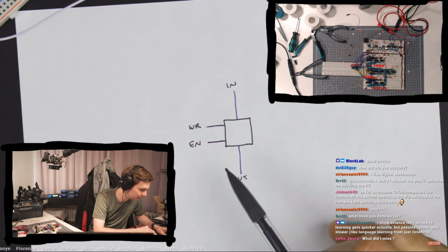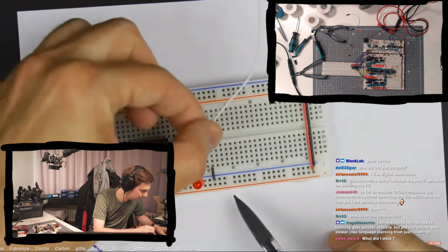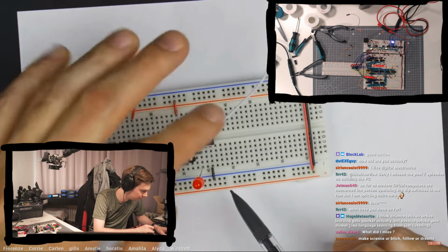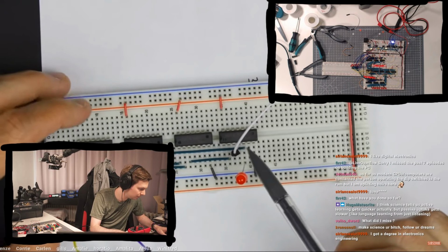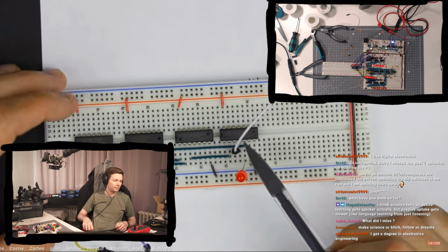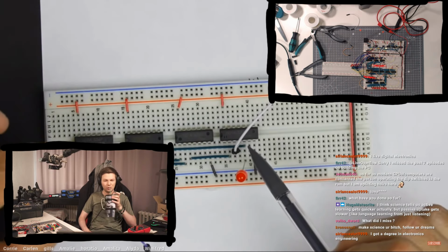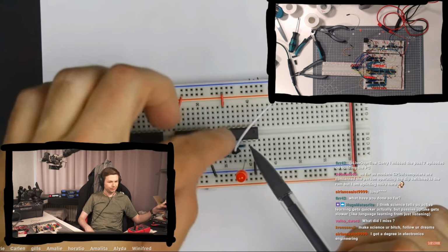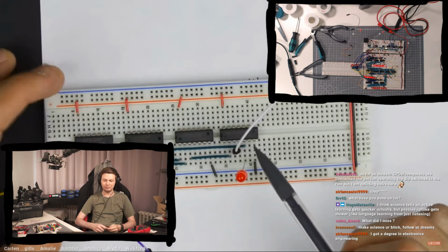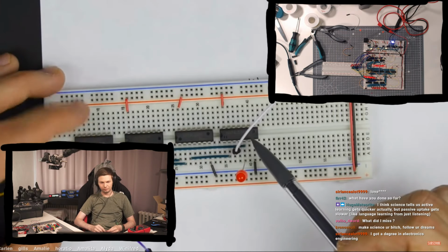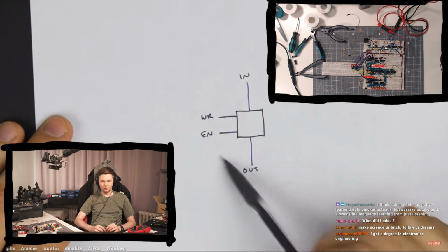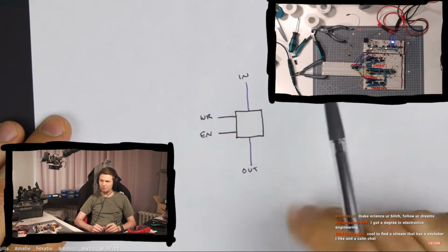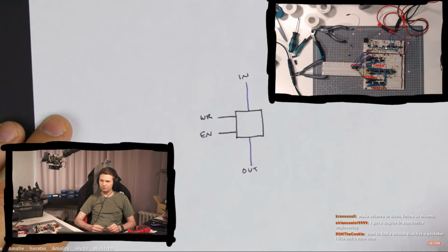Of course, the registers we've been building also have a clock signal, which for this video I'm going to sidestep. As a reminder, the clock makes this a synchronous register because even when the write signal is active, it still only reads data on the rising edge of the clock. So it's synchronized with this clock for when it's storing data. But for now, just to simplify things, I'm not including the clock here. We'll come back to that in a future video, when we talk more about the actual implementation of our memory.